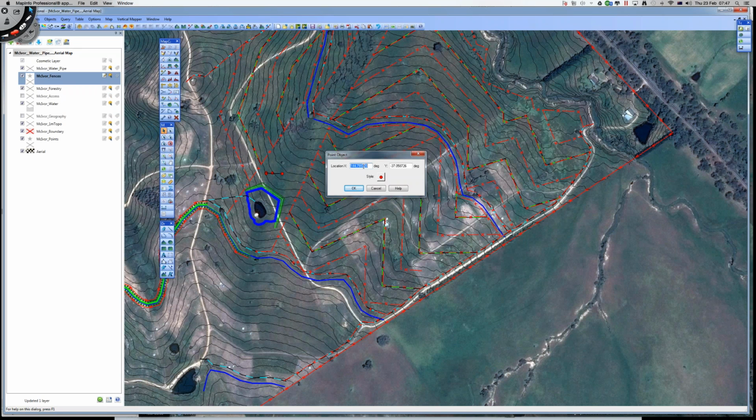See, that's the longitude and latitude of that point. So I can do that for one line, and then everything can parallel off that. So I can do another point here, another point here, another point here, and then someone like Sebastian who has a total station or an RTK or something can go straight out to the site and plot those points exactly where they are on the site.